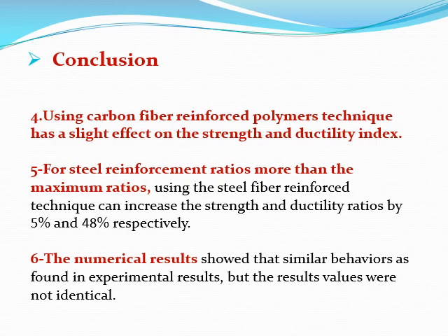Also, for steel reinforcement ratios more than the maximum ratios, using the steel fiber reinforced technique can increase the strength and ductility ratios by 5% and 48% respectively. Finally, the numerical results showed similar behaviors as found in experimental results, but the result values were not identical.